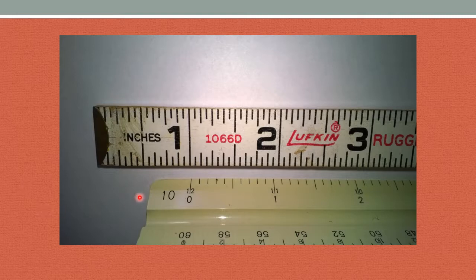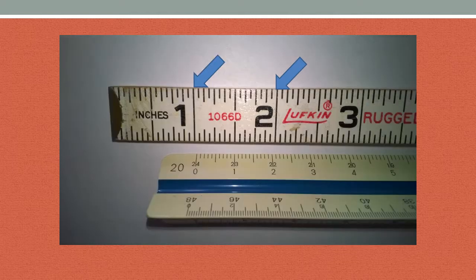Another way to look at it, here's a 10 scale. Here is a carpenter's rule. That is 1 inch. And lo and behold, it measures to the 10-foot mark. Here's a 20 scale. Here's my same 1 inch, but now I read 2 or 20.